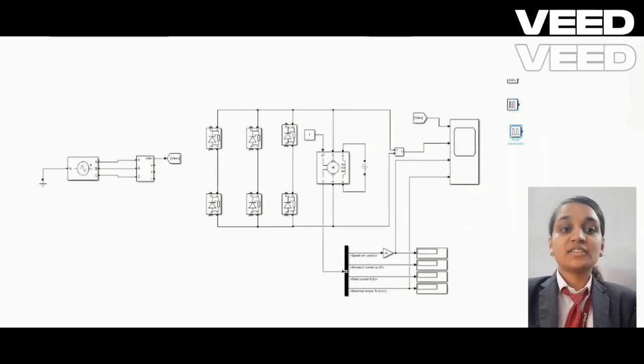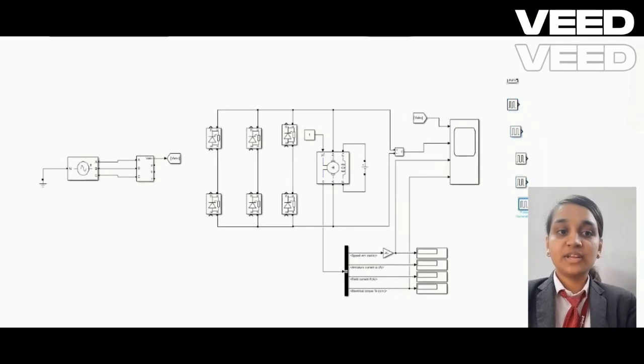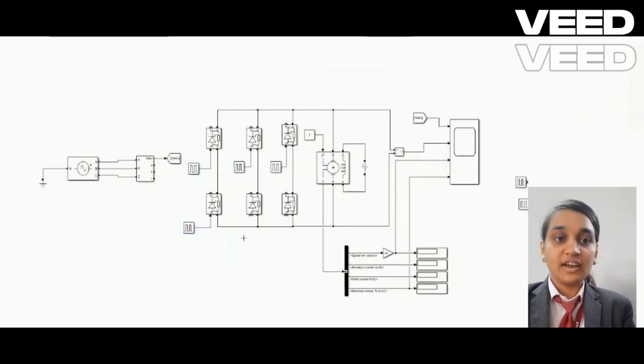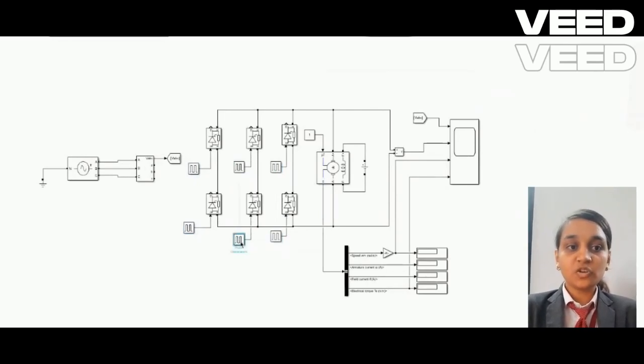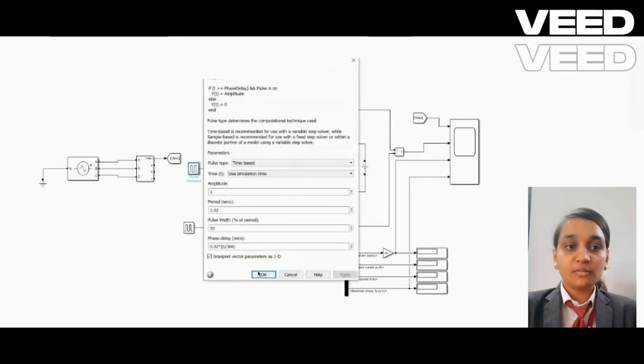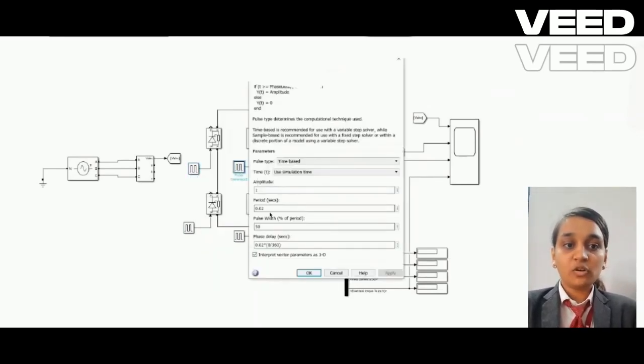My name is Anushka Shirsat, roll number 55. My topic is simulation results. The first is the three-phase bridge AC to DC converter, with DC motor and PI controller, simulated and connected in MATLAB Simulink under open and closed loop systems. As shown in figure A of Appendix A, figure 3 illustrates the waveform of the speed response of the DC motor at constant mechanical load torque for open and closed loop conditions.